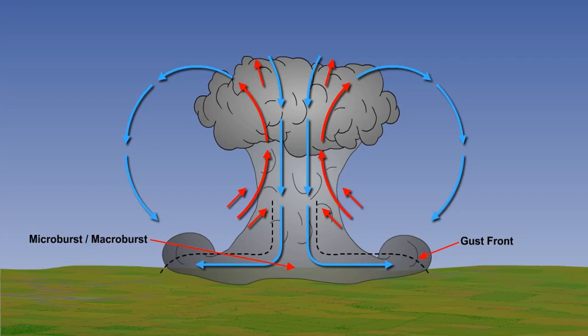You can deduce from this sequence that, no matter what type of aircraft you are flying, a microburst is a very serious hazard, and if the correct recovery action is not carried out promptly, the result could be at best frightening and at worst disastrous. It is best then to avoid the hazard rather than have to recover from it.